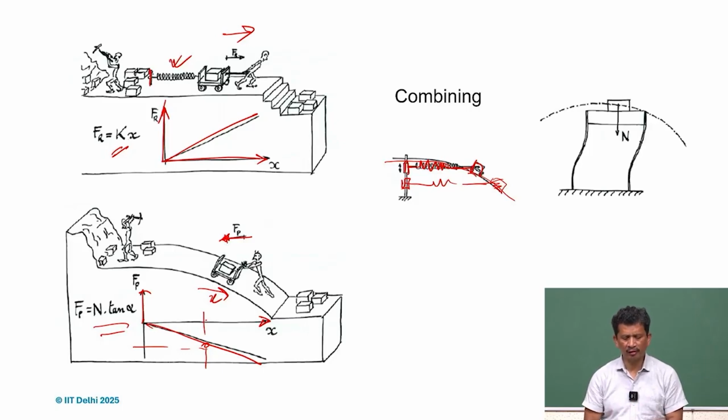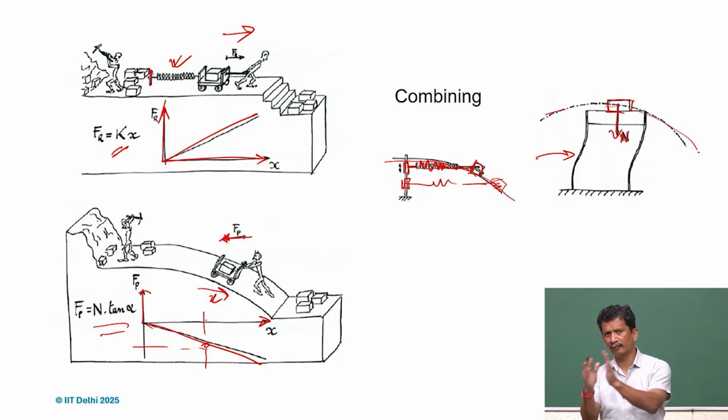In flexures, in compliant mechanisms, what is good is that the negative and the positive stiffness is intrinsic to the flexure. It's already there because it's an elastic mechanism, so the positive stiffness is already there. And with some arrangement, if we are able to get that negative part, for instance in this case, if we apply a load n, and since it's moving in this kind of ramp, there is a negative aspect.